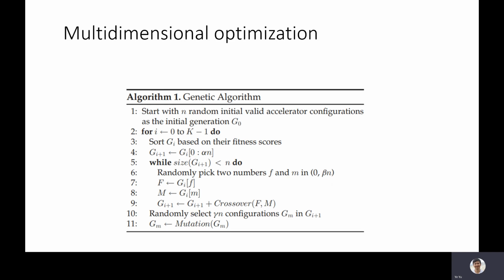Here we model the architectural optimization task as a multidimensional optimization problem. We choose performance under an error constraint as our optimization metric, where the DNN processing latency is estimated from the analytical model. The design variables defined in the architecture description file are the independent variables for multidimensional optimization. We use a genetic algorithm to solve the multidimensional optimization problem. Other optimization methods, such as integer linear programming, may also be used. Please refer to the paper for the details of this optimization.